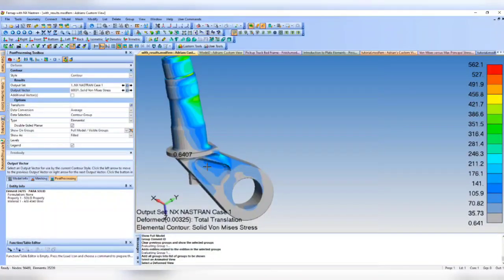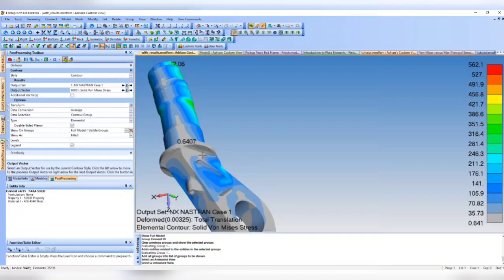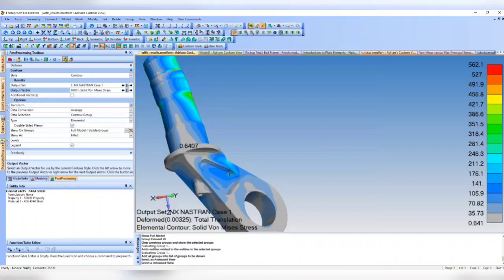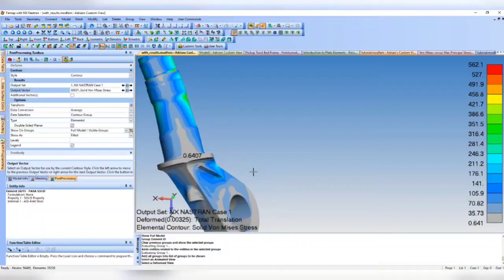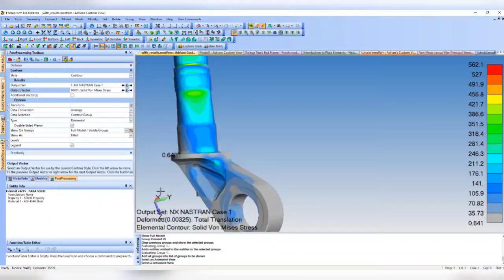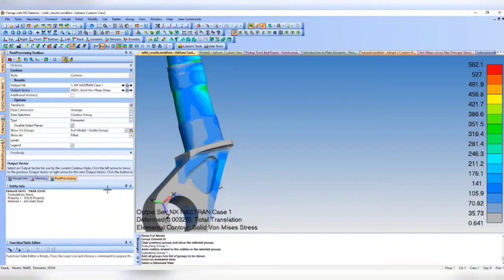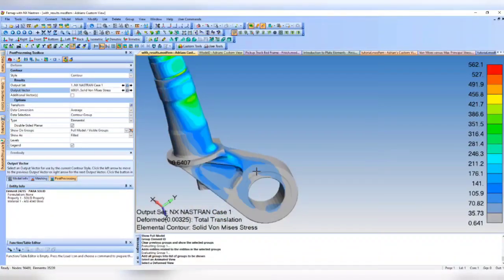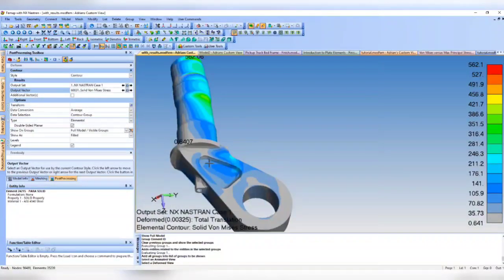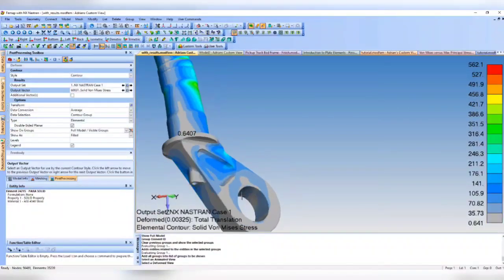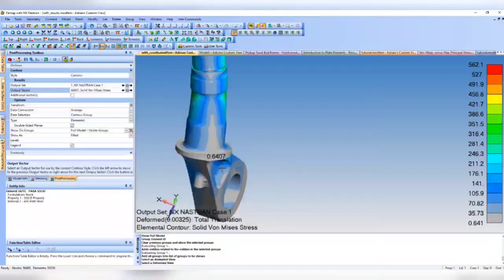You never want to obviously design a structure with a very sharp crack or very sharp crack tip. So any type of CAD that you get, the designer will always have all these radii and fillets. And so you'll never get a stress singularity in the real world environment. And typically you want to avoid that. And so, like I said, you want to always have stress relievers in your design, like radii, fillets, and so forth.